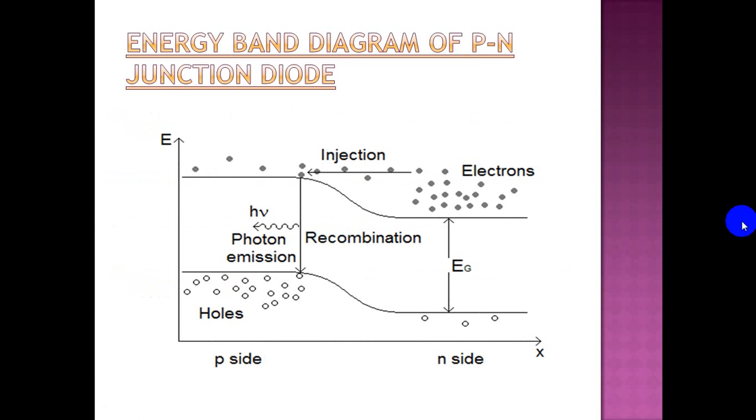When the PN junction is forward biased, the electrons in the N-type material which have been elevated to the conduction band and which have diffused across the junction find themselves at a higher energy than the holes in the P-type material. They readily combine with those holes, making possible a continuous forward current through the junction.